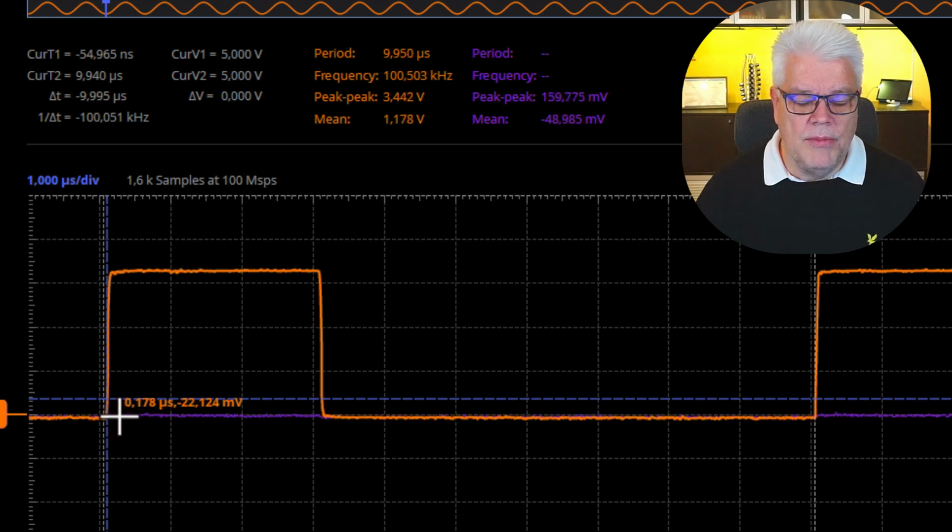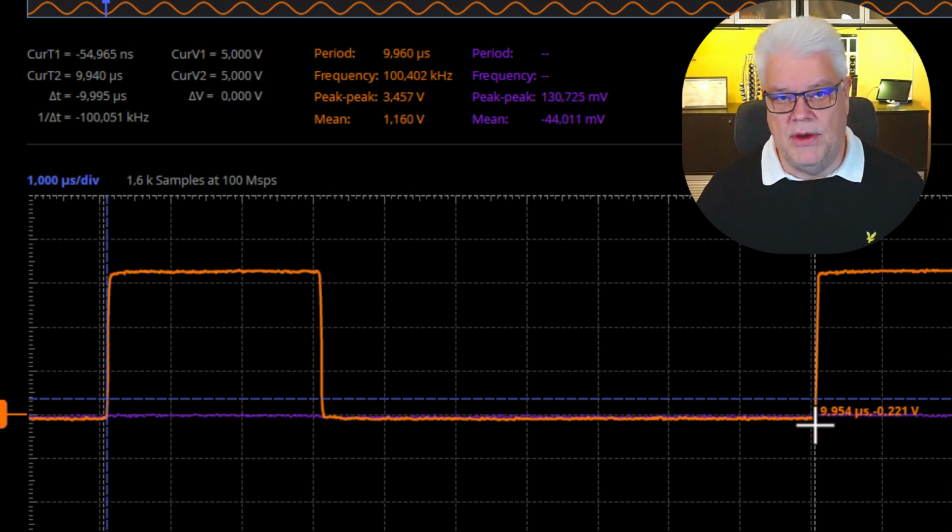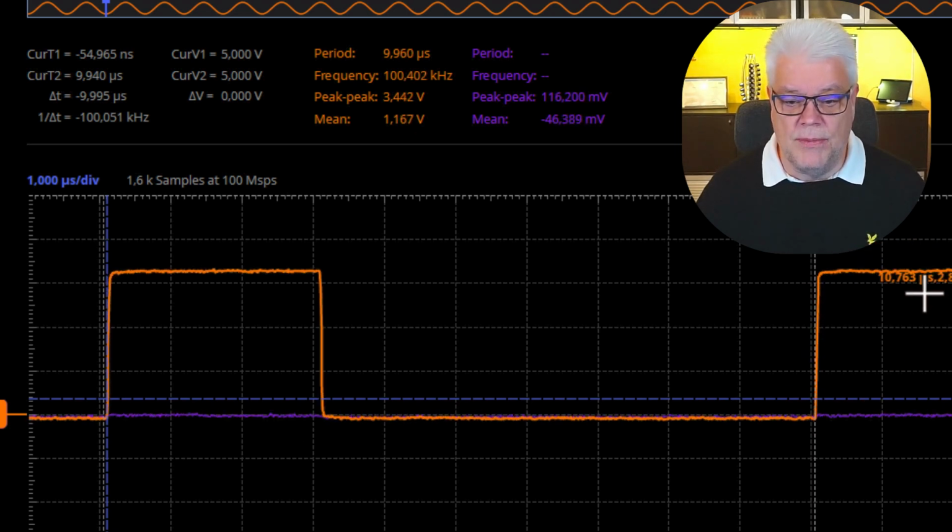And you remember the 100 that we said was the count period. If we start by thinking that we count with 0, and then 1, 2, 3, 4, 5, 6, 7, 8, 9, 10, until we come to 30, because we set the pulse width to 30. Then the pulse width says, okay, now we change to the low period, and then it continues to count all the way up to 100. And then that period is done, and then the next period comes on, and then it goes up again.